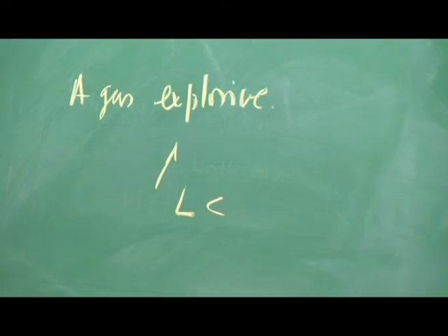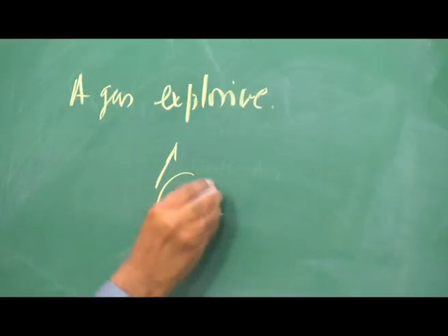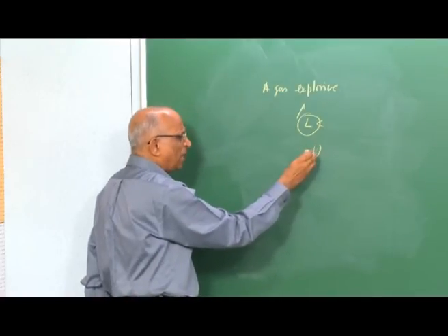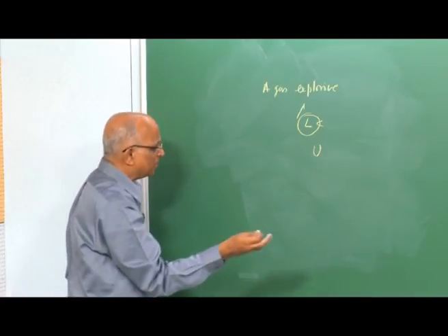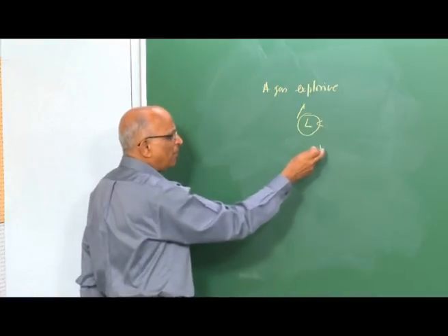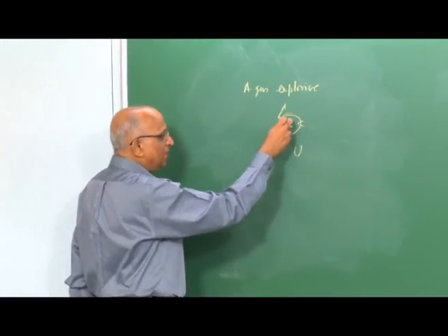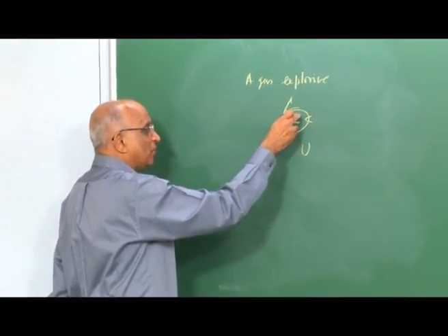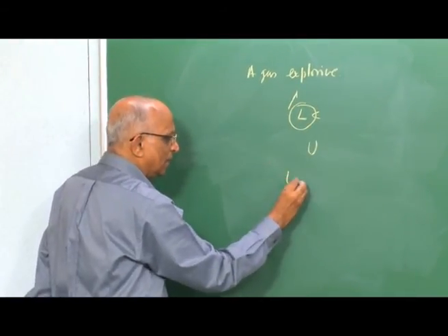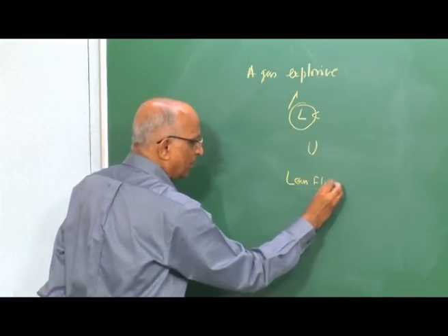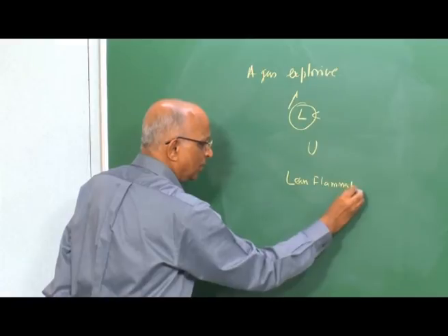In practice, the lean limit of flammability is the stronger, more important parameter compared to the upper limit, because whenever a leak happens in practice, I cannot really form a very rich mixture unless it is a very copious leak, but in general we always talk in terms of small leaks, and therefore the lean limit of flammability is an important parameter which we need to consider.